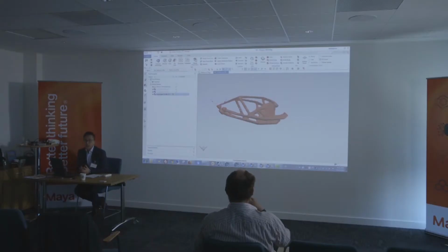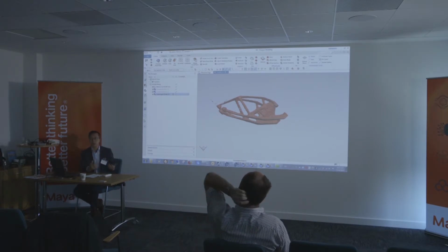The first demo is going to be focused on topology optimization and convergent modeling. Just to give you a heads up, this is what the SimCenter 3D platform looks like. Typically the way SimCenter 3D or NX works, they're both essentially the same product under different names, is we have a part or CAD environment in which you import geometries from other tools like SolidWorks or PTC Creo. Import functionality allows you to import these files natively without having to go through neutral file translation.